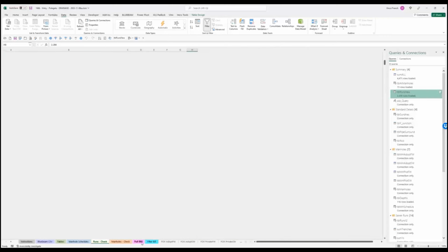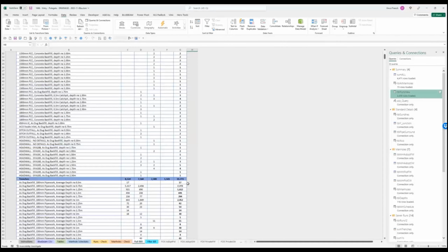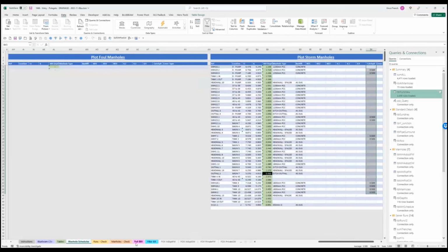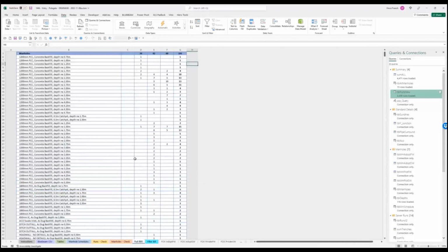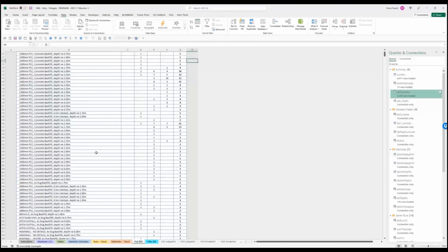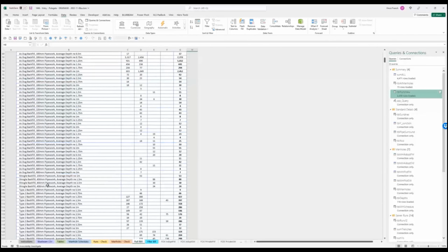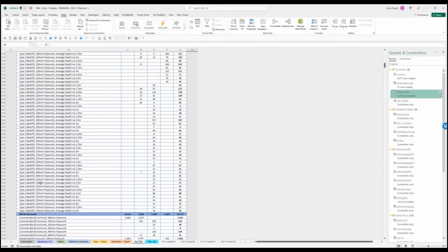So if I jump over to the full build, this is what is created by just taking the markups from Revu and combining it with these details in the tables page and the manhole schedule. There's nothing else that we're using. So we get a schedule of all our manholes, we get a schedule of all the types of trenches, as does backfill, shingle backfill for where we've got land drains, type 2 backfill where it's under hard standings.